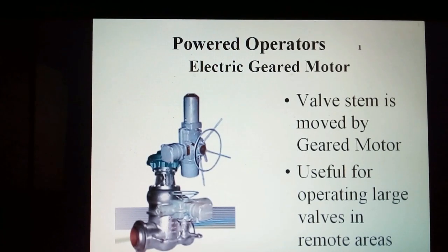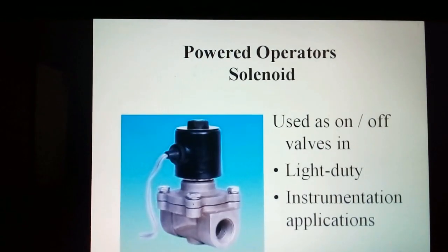Electric gear motor. The valve stem is moved by gear motor. This is useful for operating large valves in remote areas. Solenoid. These can be used for fast-acting check valves, and with on-off valves in light-duty instrumentation applications.